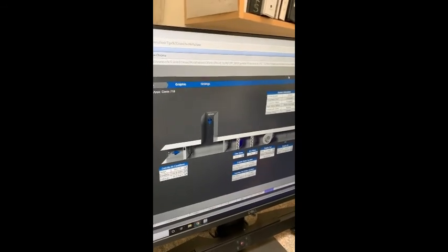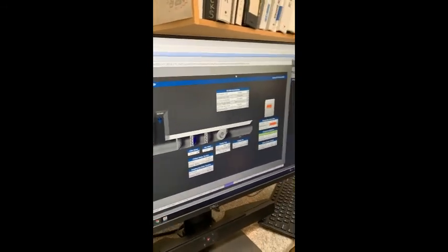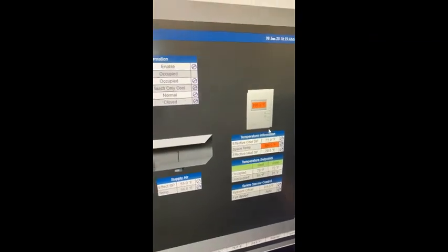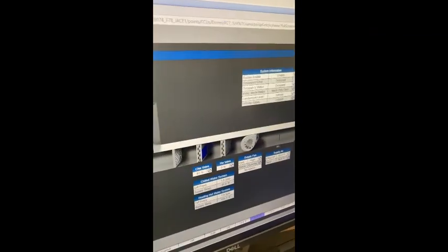It's like a duct pressure sensor or filter status. Say that value was so off that we're like, that's not a correct value. Something's wrong with the reading. So it shows a fault, and that orange represents a fault. Most likely this is that the stat has been unplugged from the wall, whether they're painting, doing something, or it's been damaged.